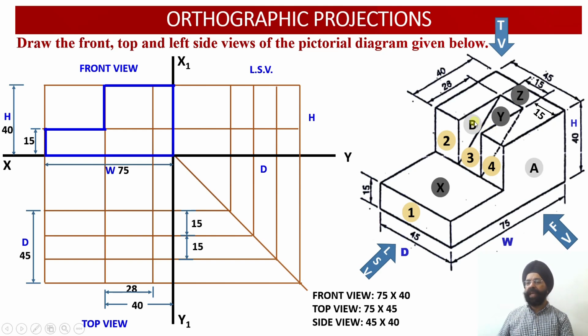So this will be surface B, but the projections of surface A and B will be overlapping with each other, but there will be a dotted line corresponding to this inclined surface which I have to draw over here. So this is the dotted line corresponding to the inclined intermediate surface which I need to draw at this point in the front view. So this is going to be my surface A. This complete surface, please check, is my surface A, and out of this total surface A, there is another surface which is a sub-part of surface A, which will be my surface B.